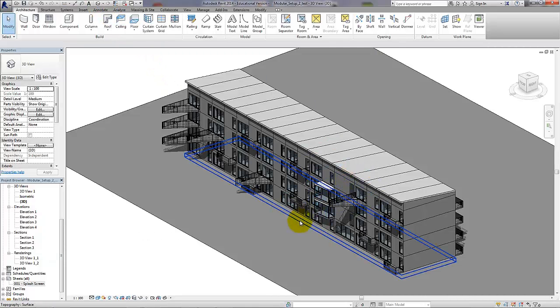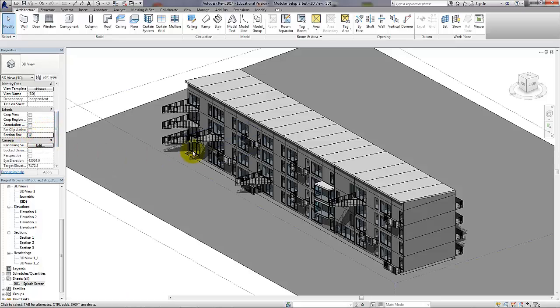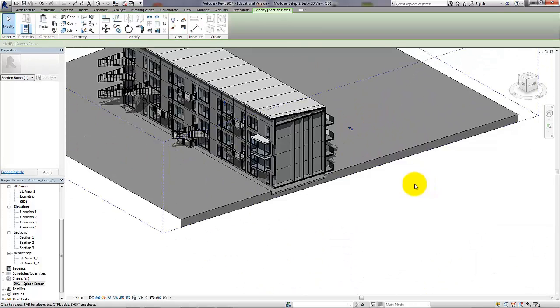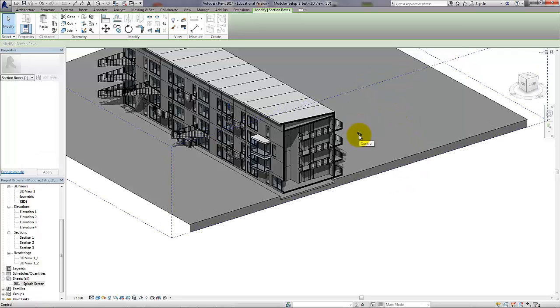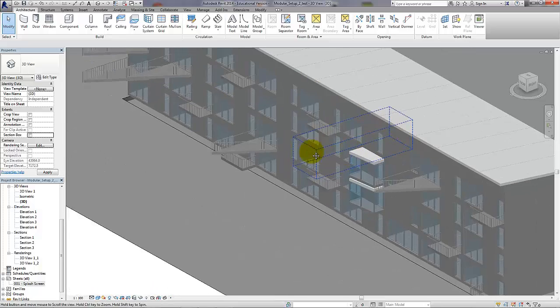Because we're dealing with drawings that are for the client, they need to show the entirety of the building. So even if you haven't finished your stair design, you should indicate some kind of stairs. So in this sample block here, I've put in a component stairs that just follows the line of the scheme as set up in the original. So that's in there.